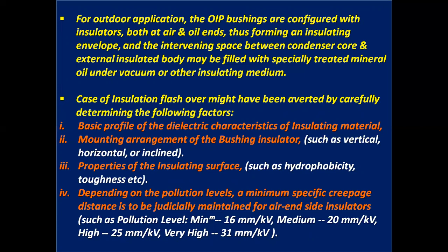Insulation flashover can be averted by carefully determining the following factors. Number 1, basic profile of the dielectric characteristics of the insulating material. Number 2, mounting arrangement of the bushing insulator, such as vertical, horizontal, or inclined at a certain angle.